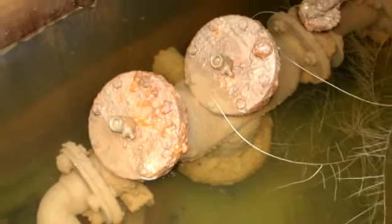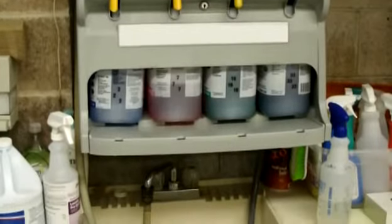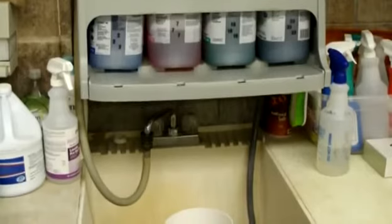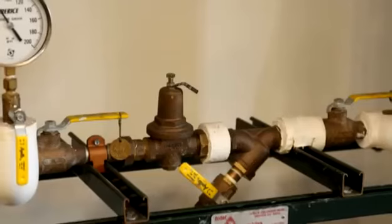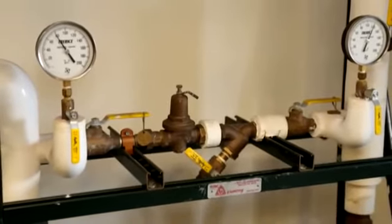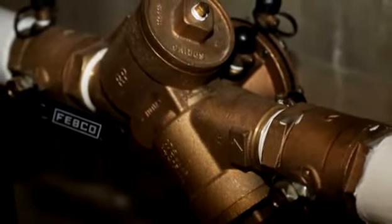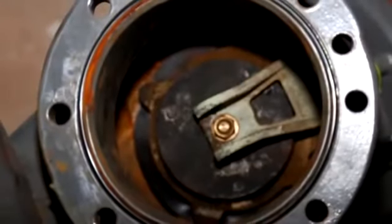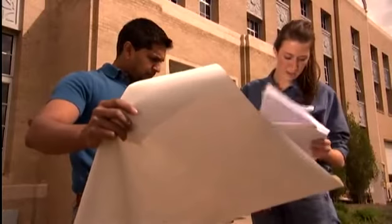Assemblies may not be submerged. Installers need to avoid vaults and enclosures without venting. Likewise, they should not be located near any corrosive or toxic fumes. Also, backflow protection devices must be secured and protected from vandalism, sabotage, and theft. Vandalism and/or sabotage could result from a disgruntled employee or someone not understanding the importance the backflow preventer represents in protecting public health. And due to the materials often used in backflow preventers, they may also be seen as a target for scrap metal.